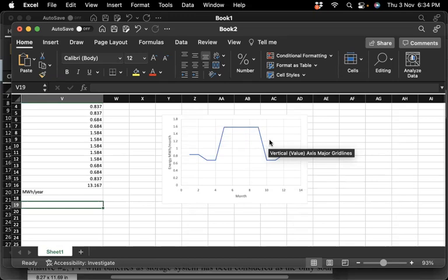To what extent is your load critical? Is it a very critical load that needs to be supplied all the time under any circumstances? Is it a PV grid connected system? This is a very important question, because if it's a PV grid connected system and you have a stable grid, then simply you don't need to design considering the worst case scenario. Because whenever your PV falls short of the load, the difference will be supplied simply by the grid. So you don't need to supply all the time.